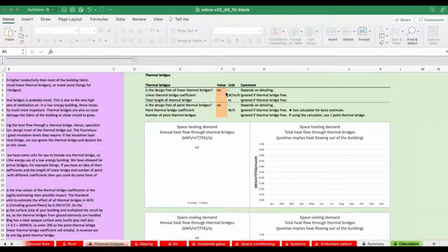So what you want to find is the surface area of your building without glazing. Find out the area of the walls, subtract the area of glazing from that, and then add to the result the surface area of the roof and of the ground floor. Whether you include the width of the walls in that will make virtually no difference, but whichever you like. Once we've done that, we multiply it by our coefficient, which is 0.1 in this case.